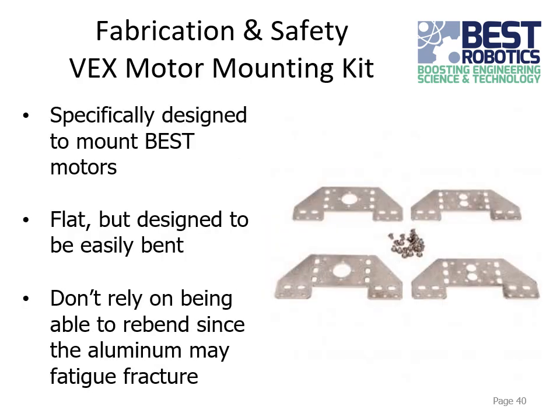For mounting your motors, you get these little motor mounting kits as part of your consumables, and they're specifically designed to work with the motors that you're given. They start out flat, like you see in this picture, but they can be really easily bent. They're designed to be bent. Just put it in a vise or something on a straight edge, and just bend it around the corner of that straight edge along those lines you can kind of see along them.